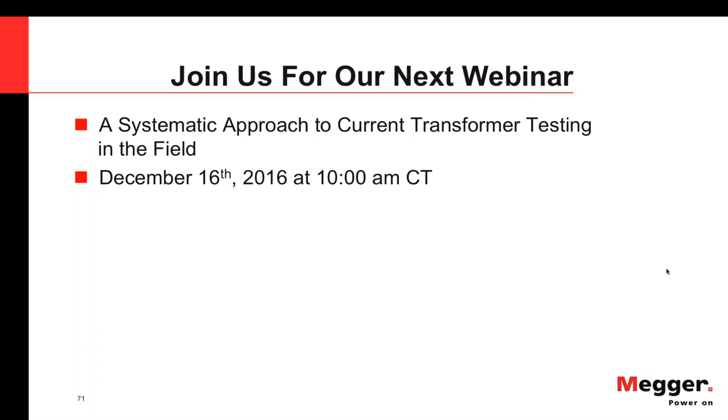You can connect the monitoring unit on the medium voltage side for power quality. The question is, how can I connect the power quality monitor directly to the medium and high voltage side? The only way to do that is by using PTs or CTs. You have to step it down. You can't connect directly to them.